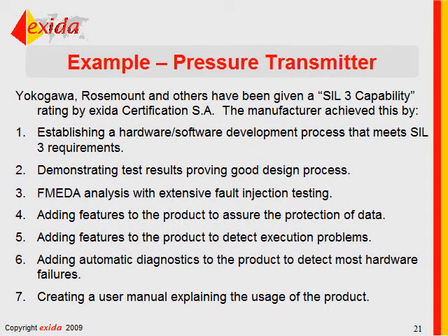I can't tell you how many times we've tested a transmitter. You kill the microprocessor clock and the output just freezes. That's no good for safety. Quite frankly, it's no good for control either. What happens if that output is frozen and the process starts going up toward the trip point? That automatic protection system won't work.